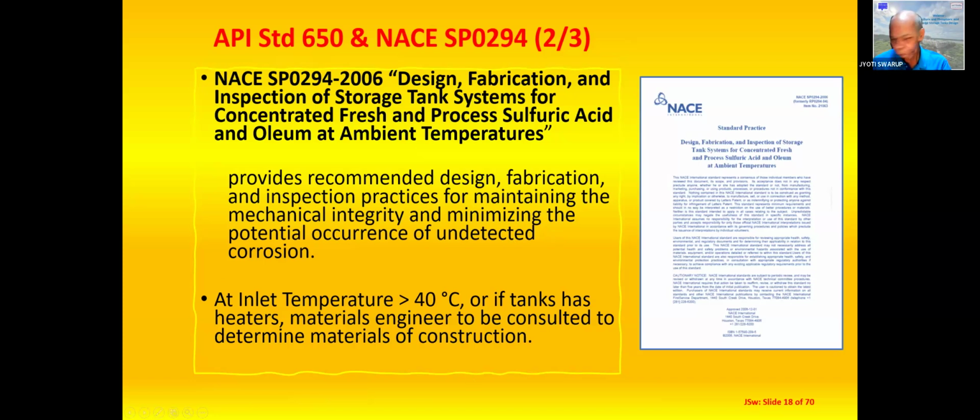This provides recommended design, fabrication, and inspection practices for maintaining the mechanical integrity and minimizing the potential occurrence of undetected corrosion. At inlet temperature greater than 40 degrees C, or if the tank has heaters, material engineers are to be consulted to design the material of construction.